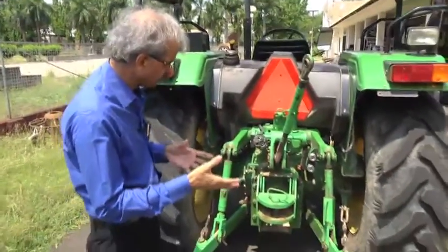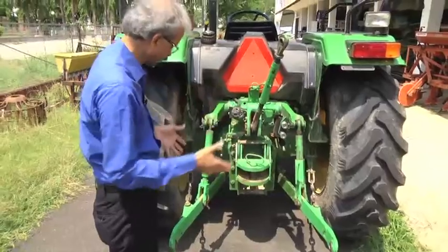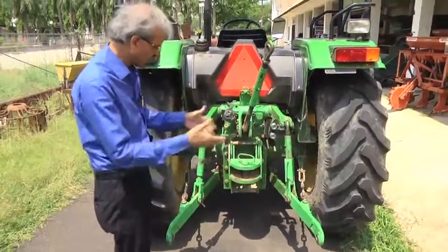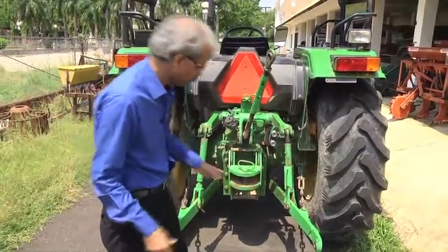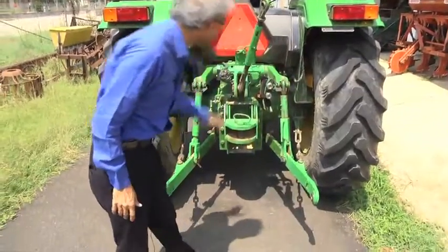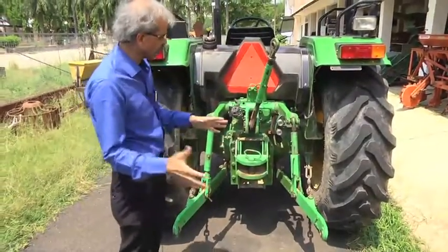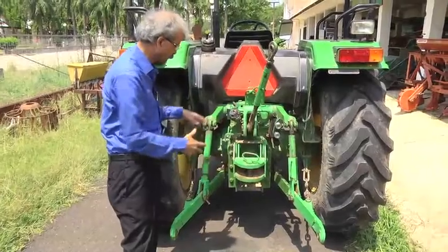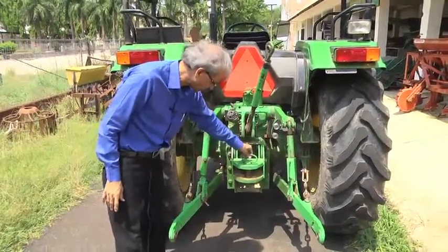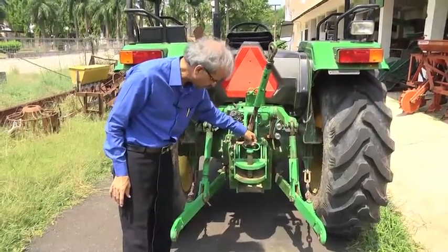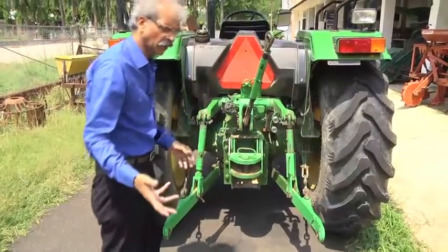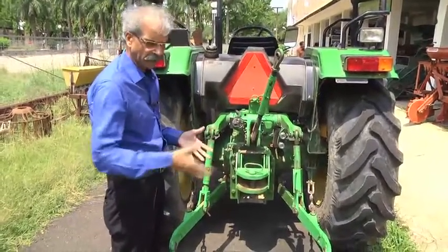Now, when we want to take the power out of this tractor, the outlet, as I said, is the PTO, which gives us about 90% of the power. The next power outlet out of the tractor is the drawbar, and this 3-point linkage, with the lower links and the top link. We have to attach the implements on these 3 points, as well as the single point at which we attach the implements which are trail type, just like our trailer or any other implement.